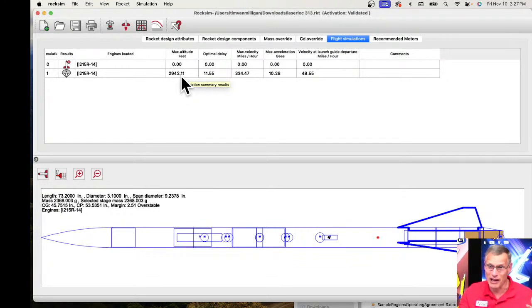So how does that happen? How did that custom come up? What I think happens is people are designing rockets so fast that they just don't check the materials, and it can sneak in there. If you don't choose a material, somehow it defaults to custom. And we've tried to find out how that happens, because this happens all the time. You're not the first person and you're not the last person that's going to have this issue. We don't know why it happens, but it defaults to custom, and that's what causes this problem where the rocket won't leave the pad.